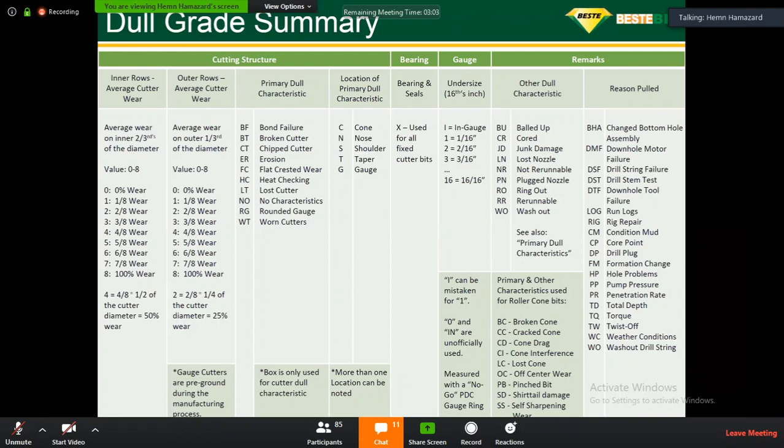If I talk about HKN, just for example, I'm pretty sure worldwide is the same. In the past, when we were drilling the exploration wells or the first and second wells in many areas, we needed more data. So we used to run wireline because our wells were vertical or near-vertical wells.